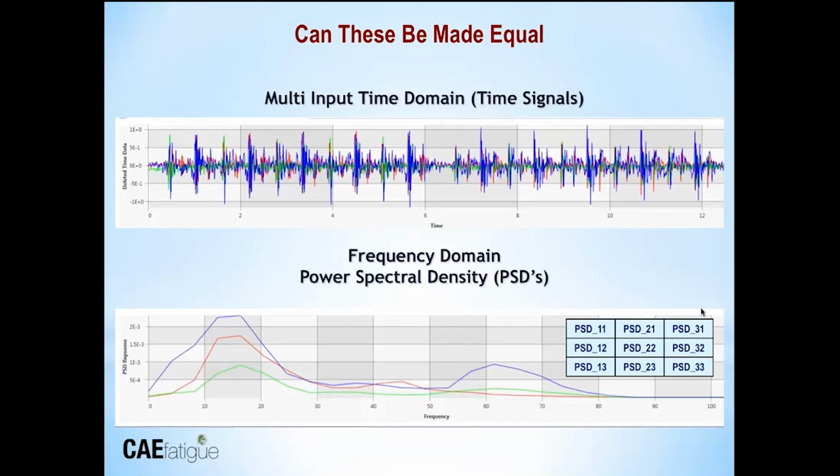On the other hand, if the front right wheel hits a pothole, and then 1 second later the rear right wheel hits the same pothole, that's the imaginary part of the correlation. And both parts are needed, and we have to take care of this when doing our analysis. That's really where a lot of mistakes have been made over the last 10, 20 years, and where nowadays we know we can do this correctly. And we can not only do it correctly, but we can manage it in a way which makes it easier for the user. I'm going to talk about that in more detail.